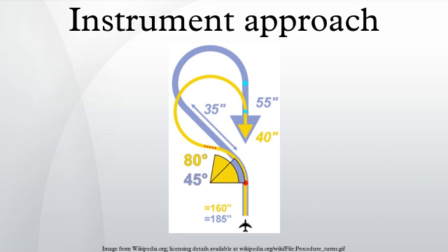When a pilot accepts a visual approach, the pilot accepts responsibility for establishing a safe landing interval behind the preceding aircraft, as well as responsibility for wake turbulence avoidance, and to remain clear of clouds. A charted visual approach is a visual approach that has a specified route the aircraft is to follow to the airport.